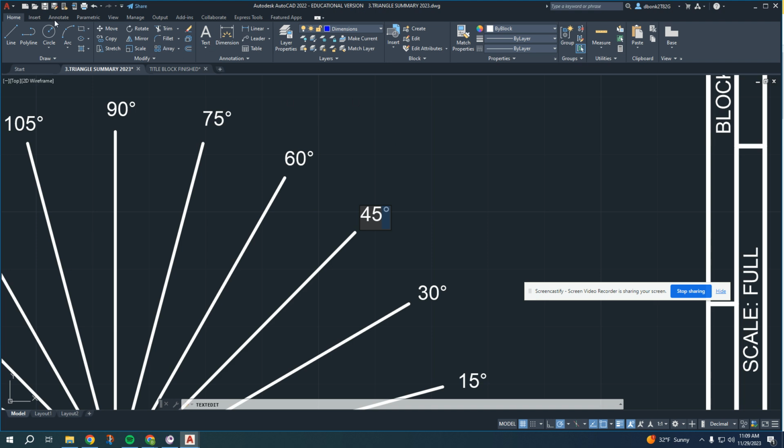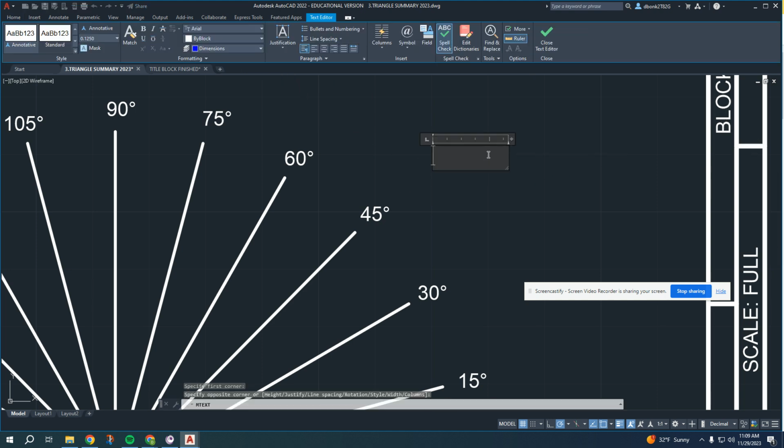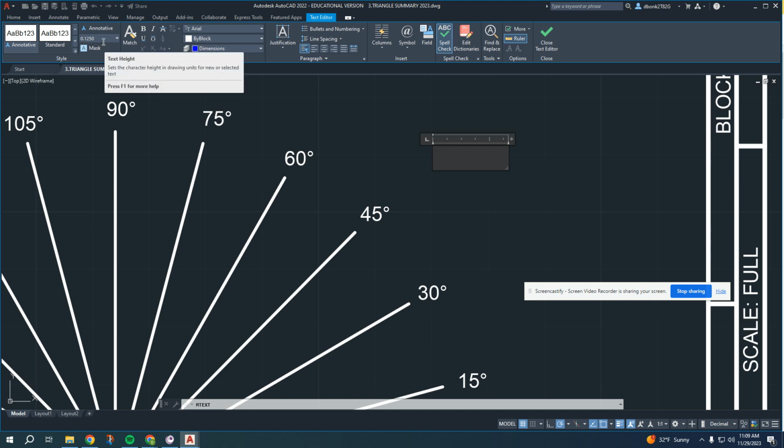When I go to insert text, I'm just going to go text. Gotta escape out of this. Go to draw text. You need to get this changed menu if your program's working the right way. You're going to have to make sure your text sizes are 0.125. That's something that people in some cases are leaving at 0.2. The text is too big.